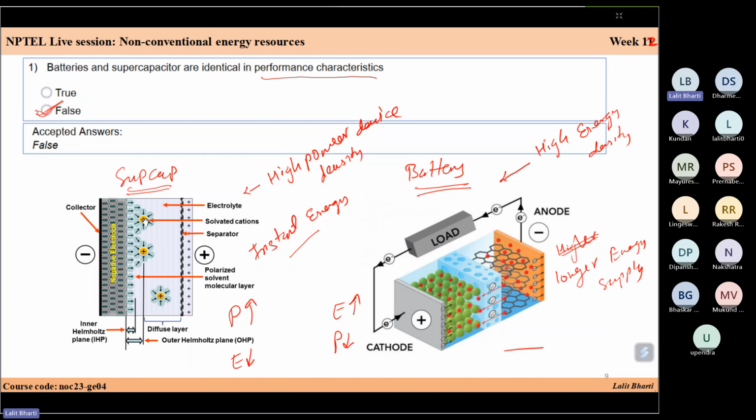So in graphene, you have a 2D layered structure. The surface area is very high and it is quite porous. If you assume these as porous structures, the effective surface area is very high. For example, the theoretical specific surface area of graphene can go to more than 2000, but the typical limit is 2000 meter square per gram. So if you assume just 1 gram of material with this specific surface area of 2000 meters square, it is very large in comparison to your normal plates.